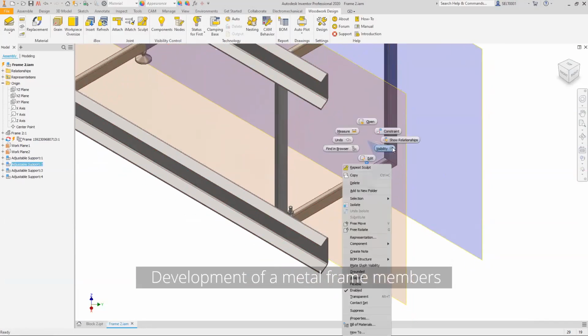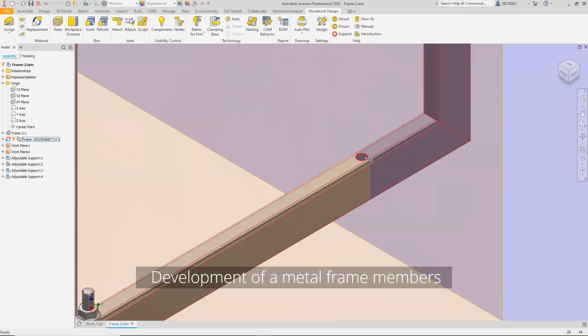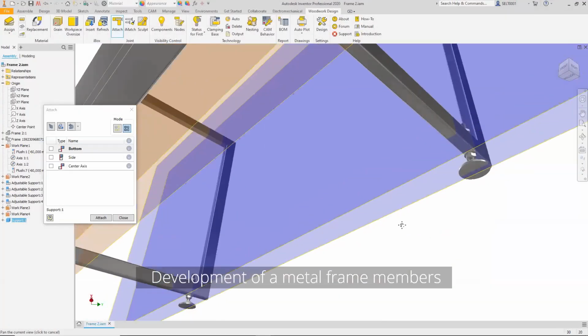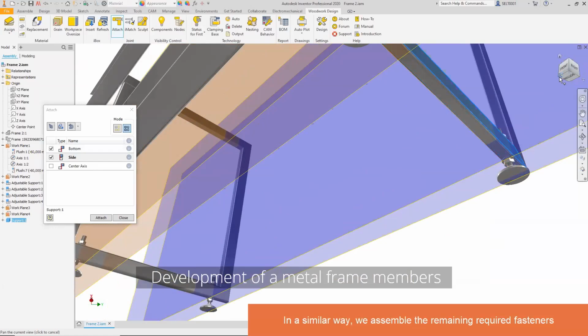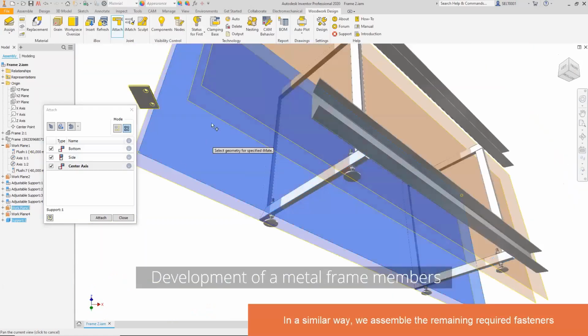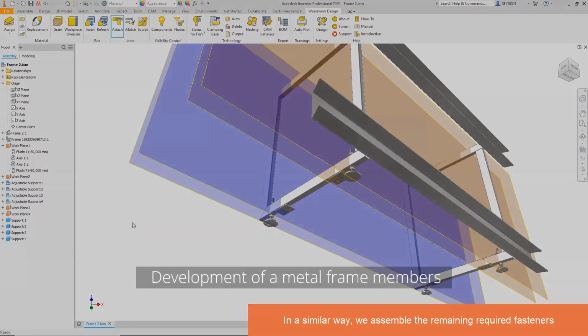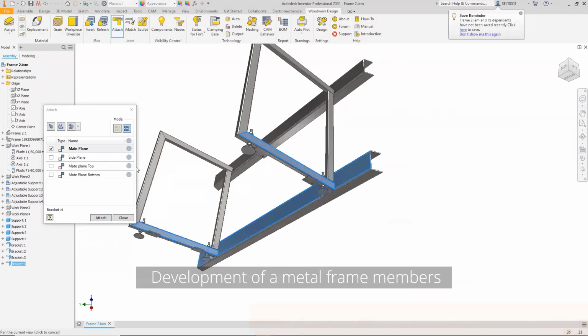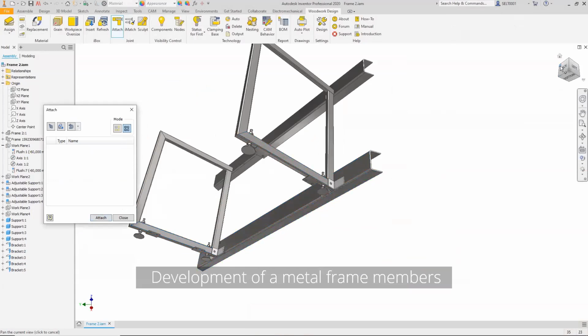Moreover, the hardware can also generate holes. As you can see, when I place the hardware, I use some sculpt command, and that's it. So we have holes in the right spot. And if we move the reference plane, the hardware moves accordingly, and the holes also change their position, which is very nice in my opinion. When we place the hardware, we get holes automatically, so you will never miss the hole position and the hardware position. They will always coincide on both joint items, which is very, very nice. And in such a way, you get rid of some mistakes.